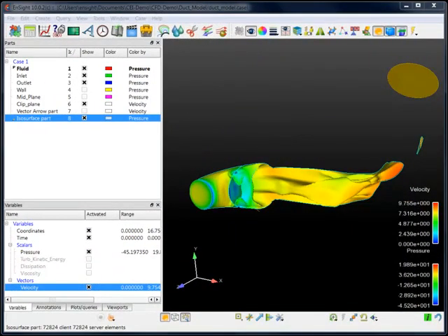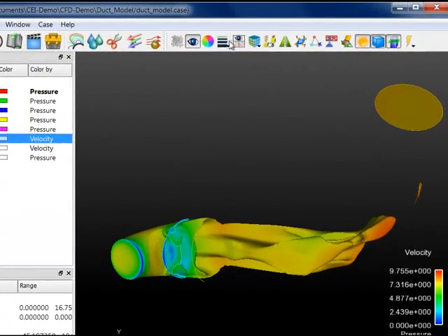Let's take a further look at the different control attributes we have inside EnSight. For the different parts we have selected, you see up here in the top right hand corner of the EnSight window that we can change things like visibility, color, line thickness, visual symmetry, for example, but also do things like filtering based off of a variable, as well as control a lot of the attributes of the part. These are what we would consider kind of adjectives to modify the particular nouns that we have selected here.